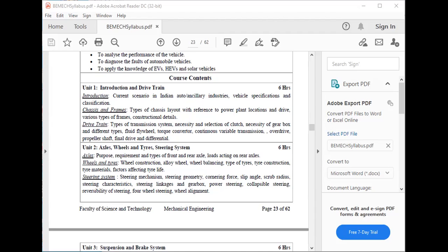It slides on the transmission input shaft bearing retainer. This is the clutch fork. Then clutch linkages are also there. A clutch linkage mechanism uses levers and rods to transmit the motion from the clutch pedal to the clutch fork. When the pedal is pressed, a push rod pushes the bell crank, and the bell crank reverses the forward movement of the clutch pedal. The other end of the bell crank is connected to the release rod. The release rod transfers bell crank movement to the clutch fork. It also provides a method of adjustment for the clutch.